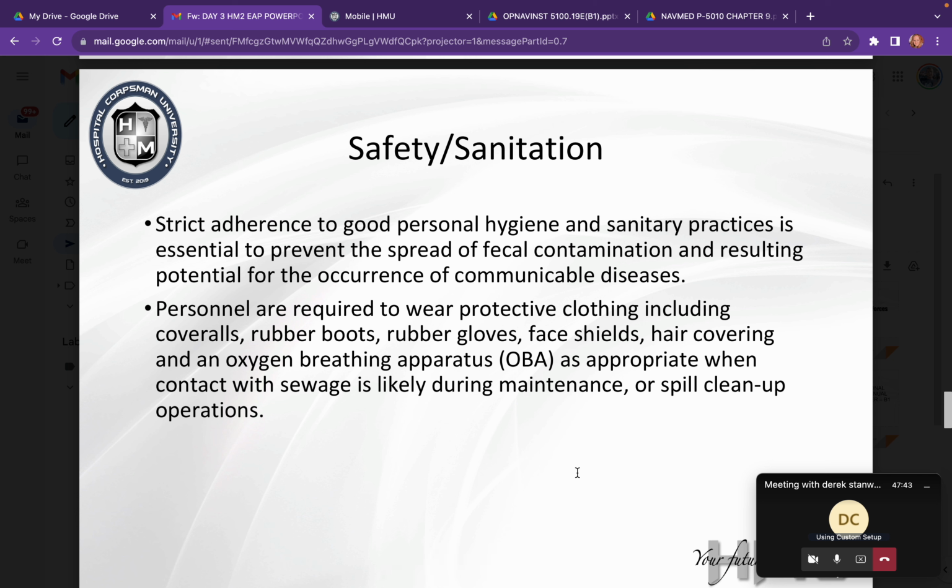You guys know what the paper towel test is? It's basically you get a dry paper towel, you place it over a pipe, and if it starts getting saturated, there's a leak. Now obviously you guys are checking the pipes, you aren't doing any of the fixing, but it's still important to know how to identify those things.